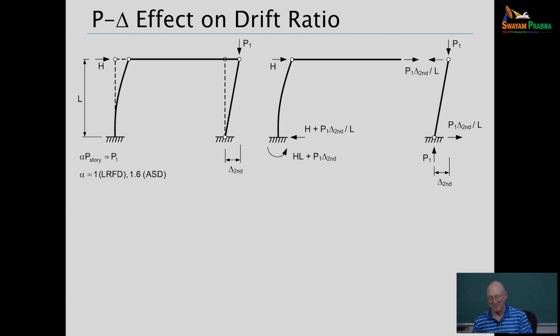But anyway, I'm digressing. So in the AISC specification, AISC likes to give no preference to one or the other officially. And so we handle things where if it's LRFD, they have a factor alpha. We can't use alpha critical in the American spec because we use alpha for something else. And that's equal to 1 in LRFD. It means, okay, we're at strength load level when we design by LRFD.